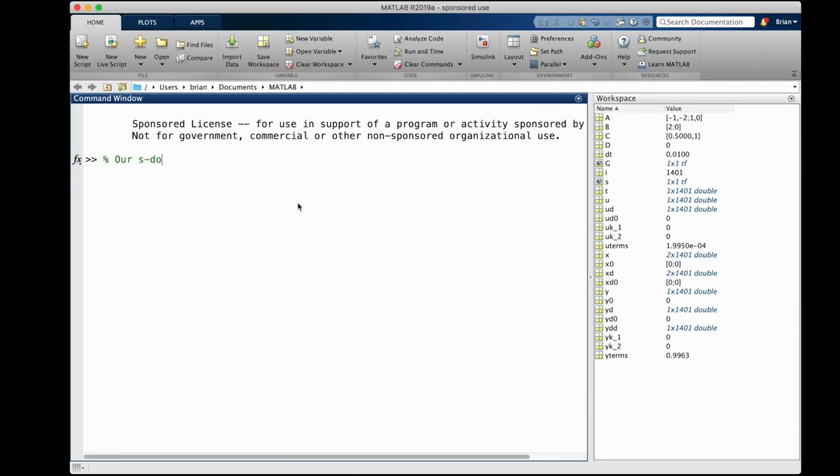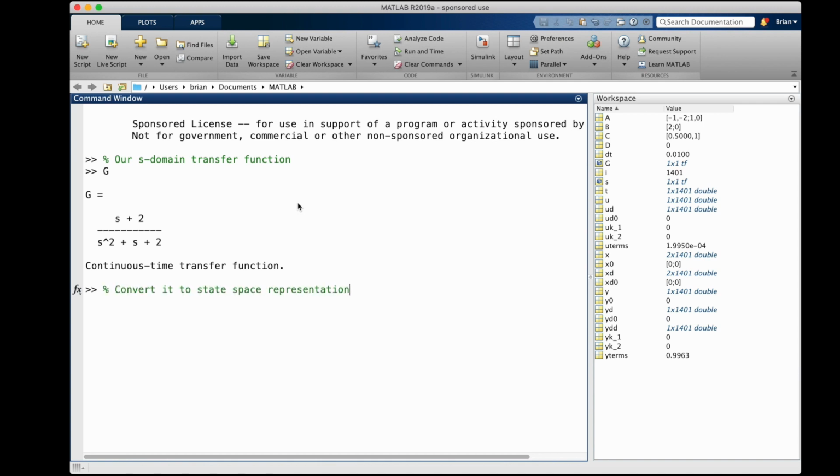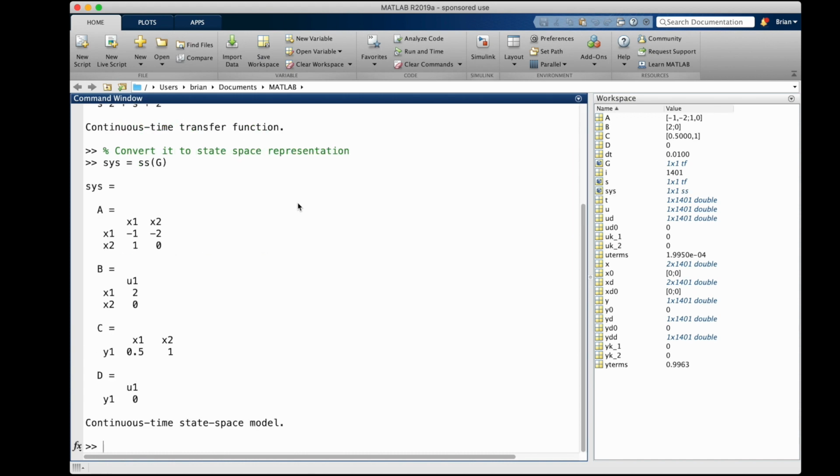This representation takes a high-order differential equation and breaks it up into a number of first-order differential equations. And if the differential equations are linear, which they're going to be since transfer functions are linear, then we can package them into matrix form. And I'm going to come back to the values of these matrices in just a second. Just realize that for state space representation, we only need 4 matrices, A, B, C, and D.